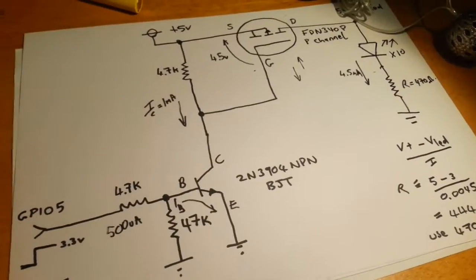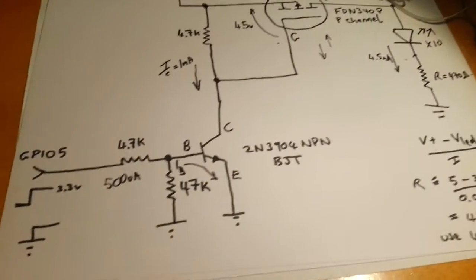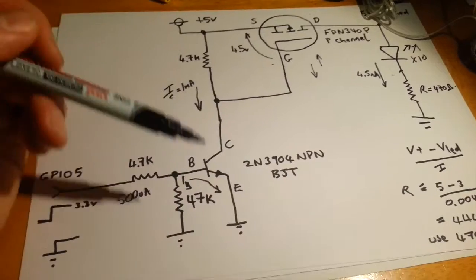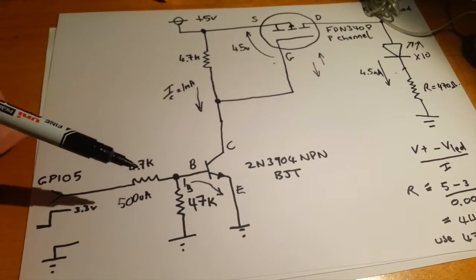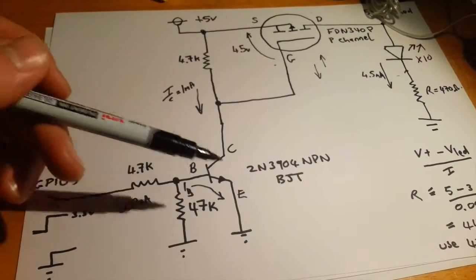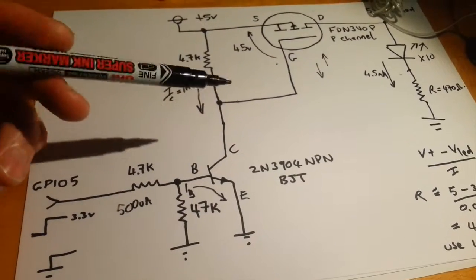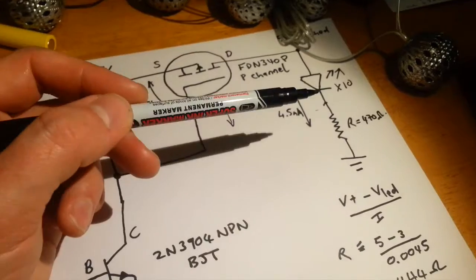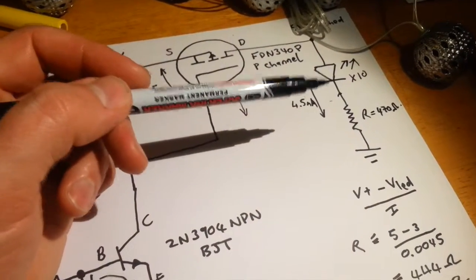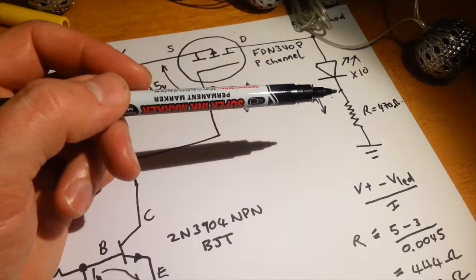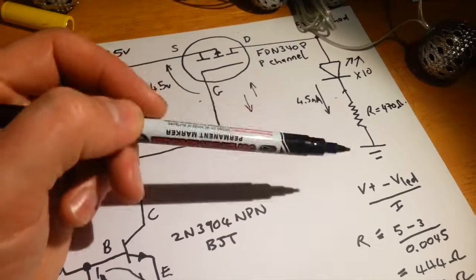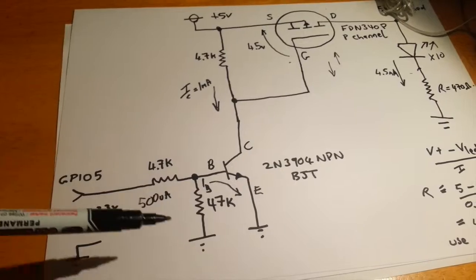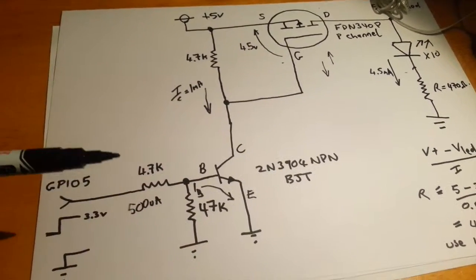As I say, if you were to build this for battery operation, then you might think more carefully about the choice of resistors because they will burn a certain amount of current whenever this thing is switched on. But in this case, and especially when I come to drive much larger LED strings that require a lot more current here, the current that's being drawn by this part of the circuit will become negligible in comparison.